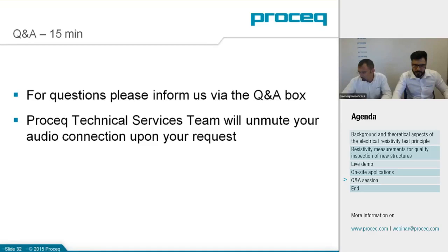And we got a question. How does a resistivity instrument work on fresh concrete? It does not. We covered that. It does technically, but it really has no meaning. Is there any difference between wet or dry specimen? Absolutely. Big time. You won't be able to test a dry specimen. It has to be wet.